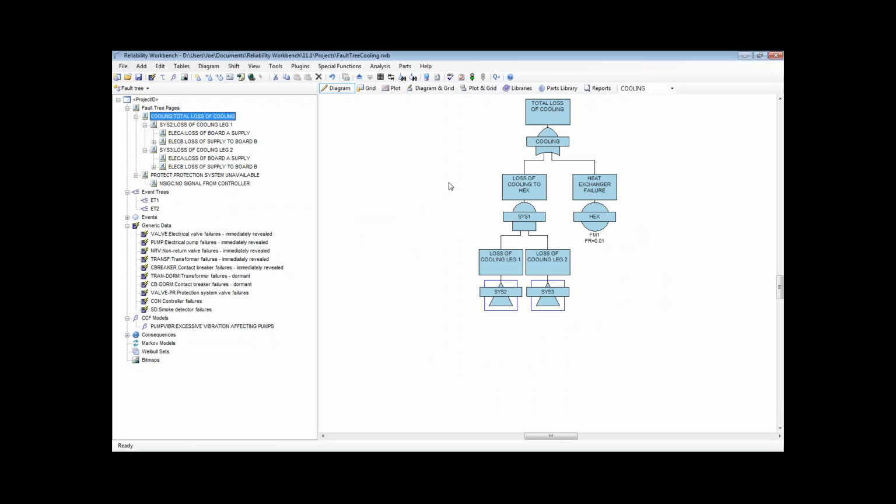And keep in mind, that's really the two basic stages of the fault tree. First, you build it, creating the logical hierarchy or the logical interaction of failures. And then you add the probabilistic information. And that's really the only two pieces of information the program needs to know: the logic of the system and the probability of failures for each basic event.